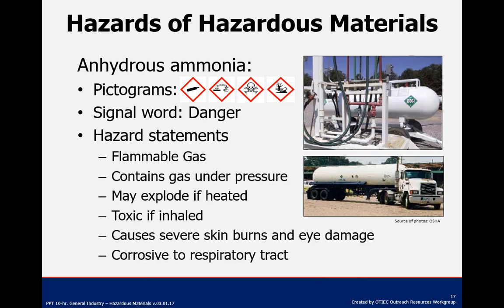So, ammonia is not strictly speaking a poison, and repeated exposure to it produces no additive effects on the human body. However, even a small concentration in the air can be extremely irritating to the eyes, throat, and breathing passages. Ammonia can primarily affect three areas of the body: eyes, lungs, and skin. Exposure to ammonia vapor may cause convulsive coughing, difficult or painful breathing, pulmonary congestion, even death in high concentrations.